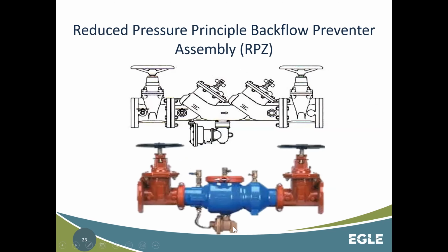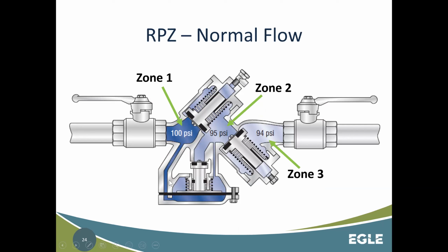That's what this thing is here on the bottom of this one and this one. These are called relief ports. So it comes down, fills the relief port, and it shuts. And what it does is after it shuts the relief port, it fills the chamber between the two different check valves here, and it opens it. And then this opening of the check valve, and then it opens the second one, and the water flows through in that fashion.